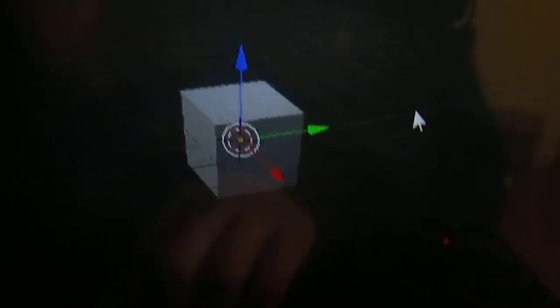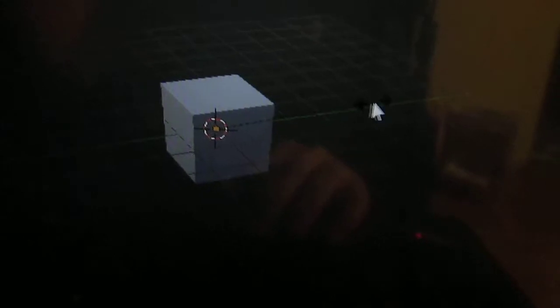After you select curve, when we come back here, you can just press S on your keyboard, which means scaling. After you press S, you'll be able to scale the object by moving your mouse. We need to scale it until we are able to see it. Now it should be big enough because we are able to see it now.